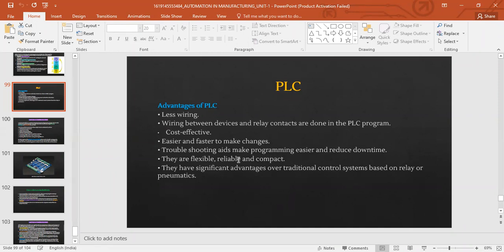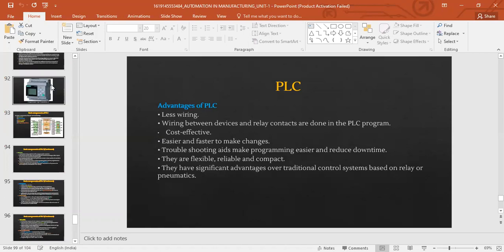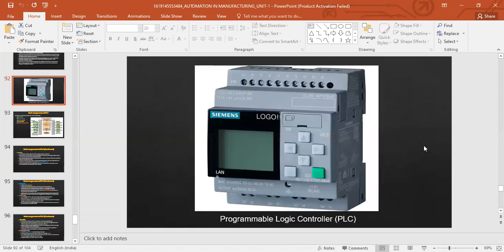When you have this display unit, and it interacts with you as to what is wrong, that will make troubleshooting easier to find out where exactly the fault is. Either the program is wrong, or there's some problem with the program structure, or some input device scanning has not been done, or a problem with the input devices, or a problem with the output devices.